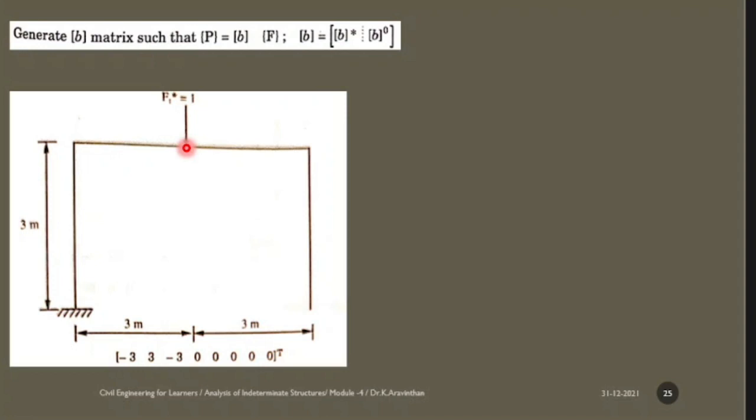So that's why you will be not having the moment at next joint, these two, and at this joint, that is joint C. What will be the moment? Load into distance. Yes or no? 1 into distance is 3. Now, why you are not accounting the moment is, here you can see at the joint D, what is the support here?